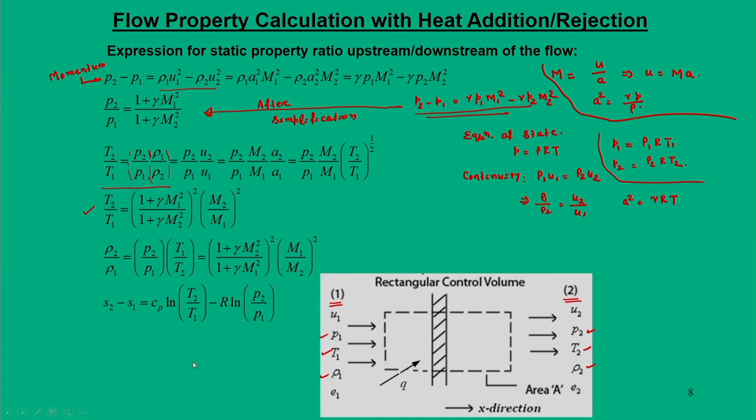So, obviously, when you know the pressure, temperature and densities, pressure and temperature ratios, we can also evaluate what is happening to the change in the entropy. Now, effectively this particular expression does not explicitly focus on the heat addition process, but this heat addition Q has already changed the property ratios P2 by P1 and T2 by T1, and these ratios are mentioned here.